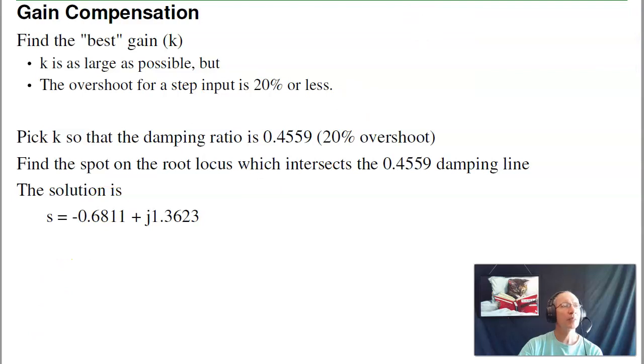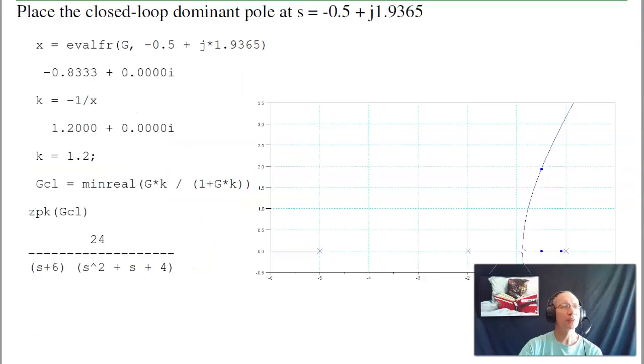So what that example did is it showed root locus actually works. If I draw the root locus and then pick different spots on the root locus and calculate k and plug it in, that's the response I get. Putting the pole right here at minus 0.1 gave a real pole, no overshoot, 40-second settling time. Putting the closed loop pole at minus 0.5 made it an 8-second settling time. -0.5 plus j1.9 gave an overshoot, oscillations at 2 radians per second, 8-second settling time. The root locus is actually predicting the behavior of the closed loop system.